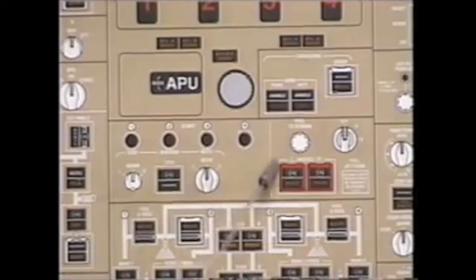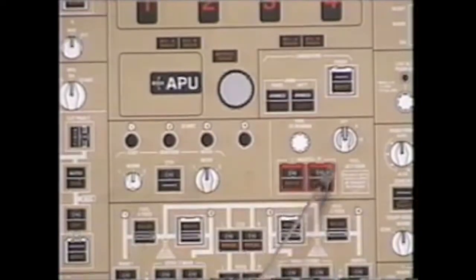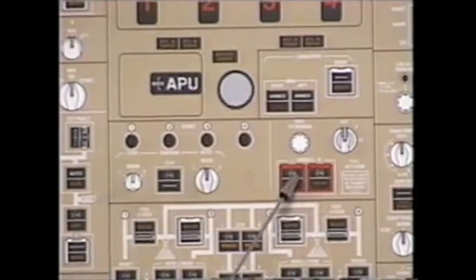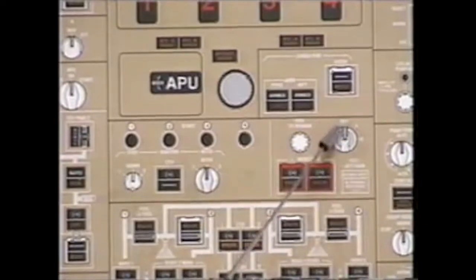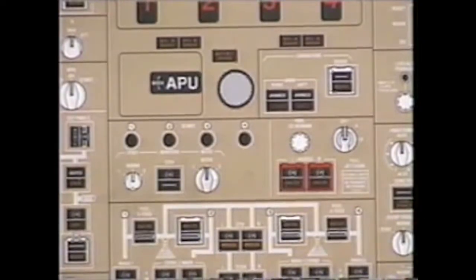To the right is our fuel jettison control panel. We have the jettison nozzle valves left and right, the jettison controller, and the fuel to remain. The jettison nozzles, the important thing to remember here is even if you're on the ground with the jettison selector to the off position, you can physically open the left and or right jettison nozzles. Not something you really want to do. Please keep in mind if maintenance is fueling your airplane, you would be defueling the airplane. The only time we should use these switches is in accordance with the fuel jettison procedure.